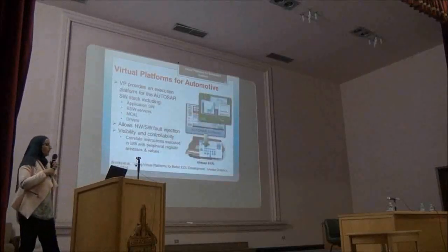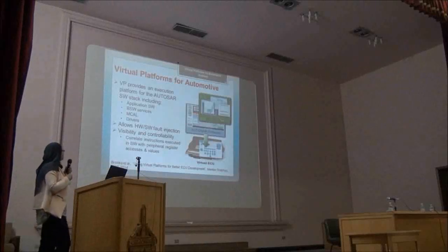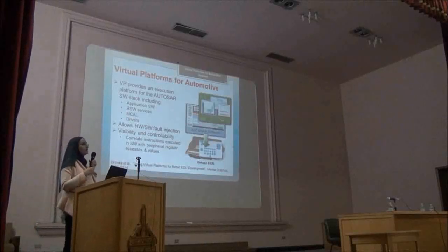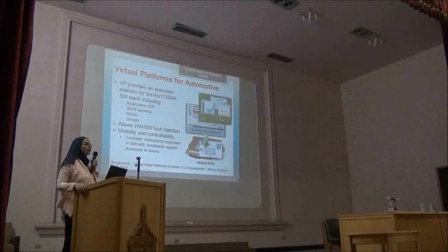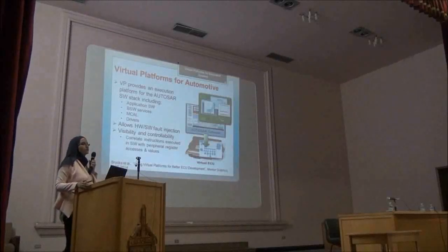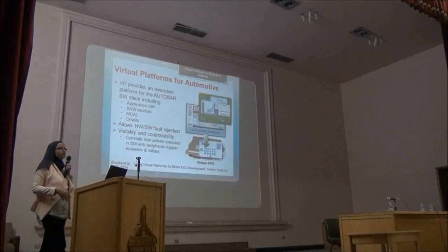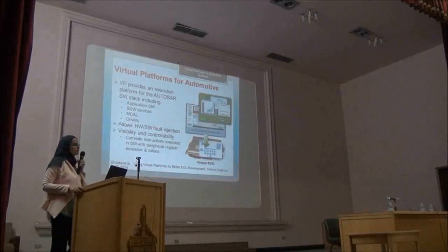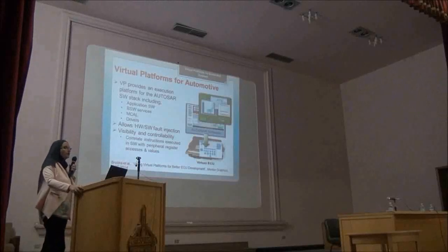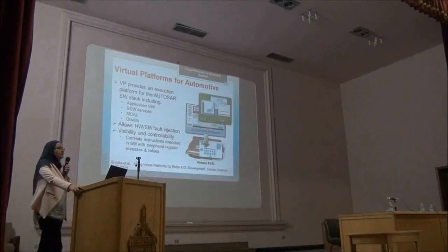So we have a virtual ECU instead of the real ECU, which you can run on your PC, and then you can run the whole AUTOSAR software that Dr. Bassem will introduce to us shortly, with the application software, the basic software, the microcontroller abstraction layer, the drivers, all of these running on the virtual ECU.